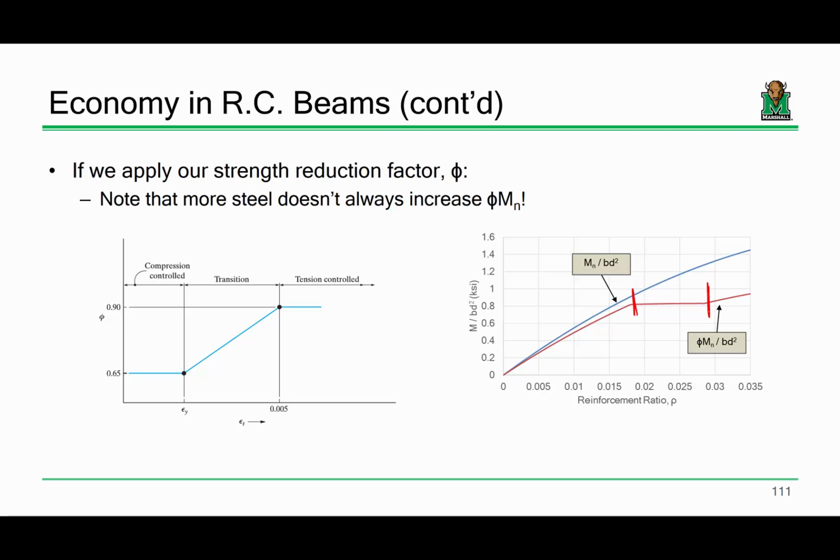So when we start putting the steel in there, it's going to start rising for its capabilities of reinforcement. Eventually it will plateau. When you get into transition regions, you start upping the steel, you don't get much benefit out of it. You just don't. But eventually you'll start getting something. But that's a good question.